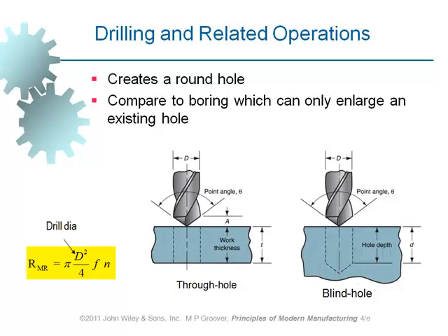And when we are computing the depth of cut, please note that we've got to actually consider the amount of the drill bit which is used at the tip of the cutter, which is not considered as the whole depth. Whole depth is considered from the top surface up to the end of the hole when we've got the same diameter. When diameter narrows down, it's not considered as part of the hole or cutting depth. So we've got to take this amount of penetration of the cutting tool into consideration.